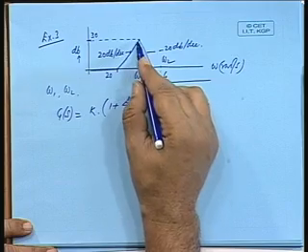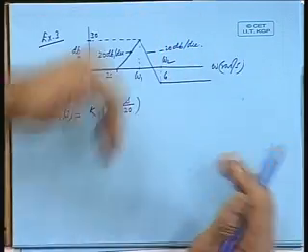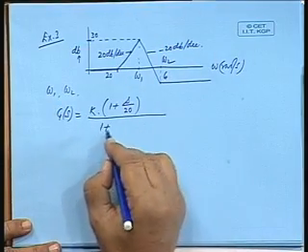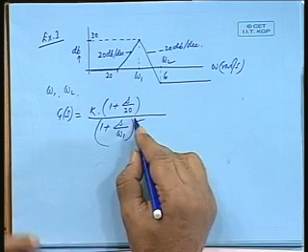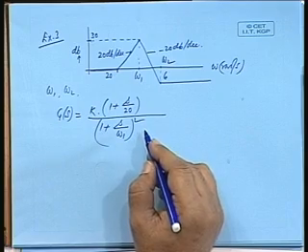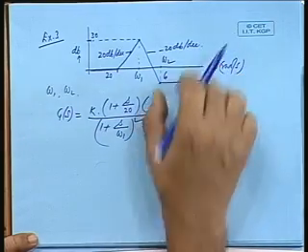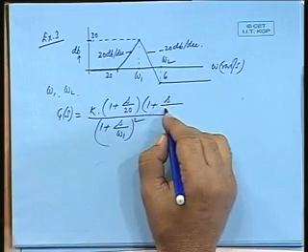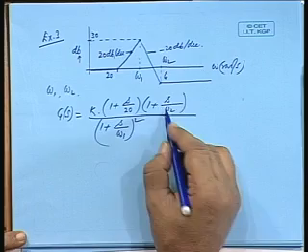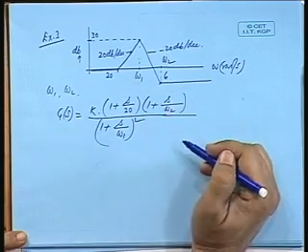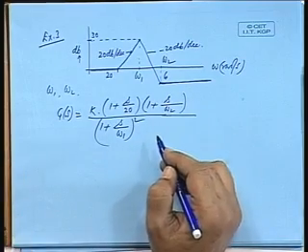Then at omega equal to omega 1 there is a fall of 20 dB, it becomes minus 20 dB. So, there is a fall of 40 dB. So, 1 by (s plus omega 1) whole square. The whole square term will give you a slope of 40 dB per decade. Is that all right? And then at omega 2 again that is restored. So, 1 plus s by omega 2 will be the other factor which will finally make it horizontal. Now, what is omega 1 and omega 2?